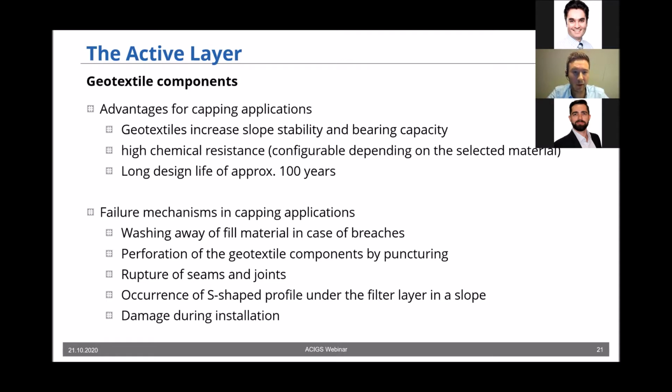But of course, there are also failure mechanisms with geotextiles in capping applications, and I also want to show them here. You can have issues like the washing away of filled material in case of breaches. You can have a perforation of the geotextile by puncture. This comes from the installation process. When it is not done properly, you might have puncturing. You can have issues with the rupture of seams and joints.